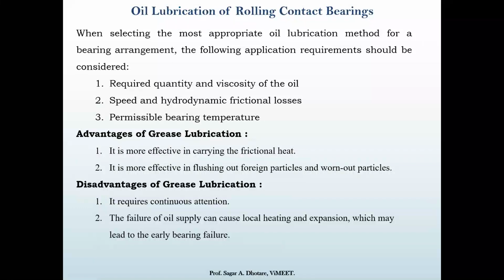We need to check whether the seal is properly closed or not, and whether the oil level is going down, because as the temperature increases due to heat, the level of oil gets reduced. So we have to maintain the level of oil. The failure of oil supply can cause local heating and expansion, which may lead to early bearing failure.